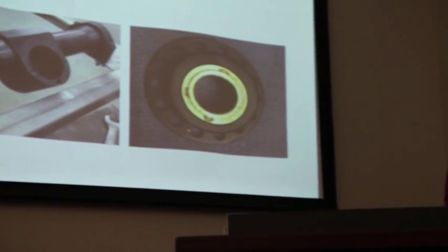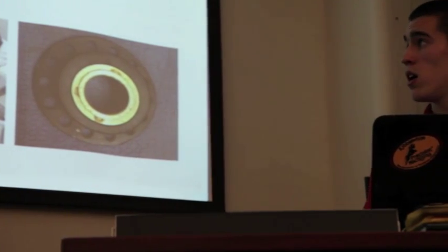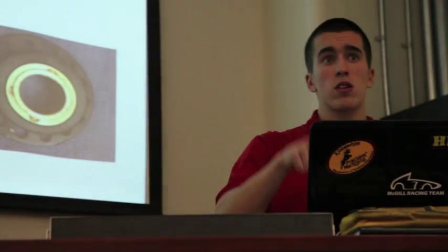So it was a lot harder for the driver to steer the wheel, especially in the slaloms, because if you're static, the friction is static, so it doesn't really increase the force the driver has to put in. However, in slaloms, you have to put a lot more force back and forth. So that was where I'm driving. He definitely noticed that the steering was a lot heavier, and it was too hard. It made him tired to the extent where he was getting a bit slower, and it was harder for him to aim accurately in the corner.